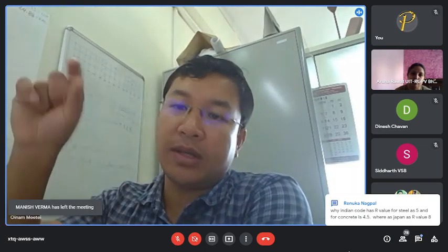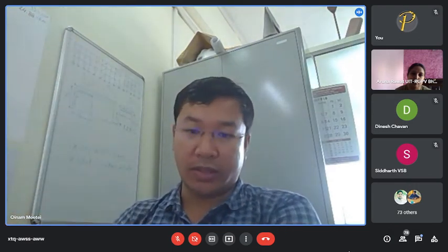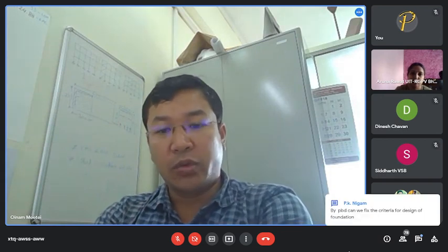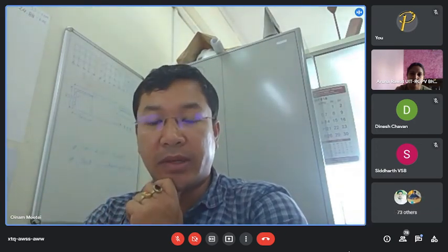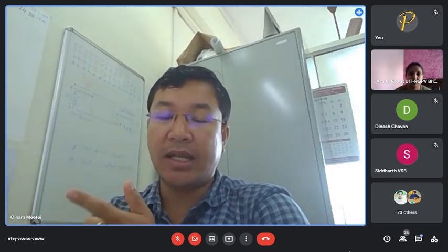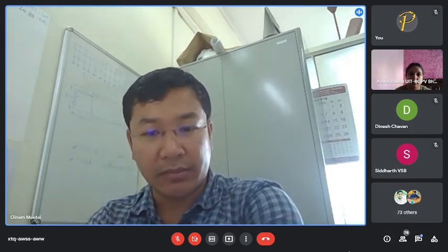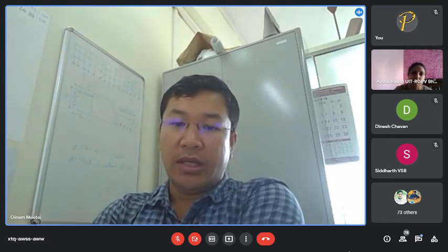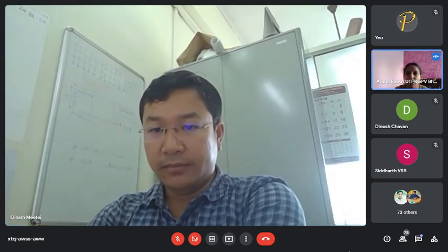If you record all the responses and plot them, you'll get a kind of half normal distribution. That's how you get the structural performance through incremental dynamic analysis. And this is for one ground motion. For one ground motion, you might do 40 analyses. Similarly, if you use 10 ground motions, 10 into 40, you need to do the analysis 400 times. That's how we did the incremental dynamic analysis for different ground motions. Yes, sir. There is one more question.